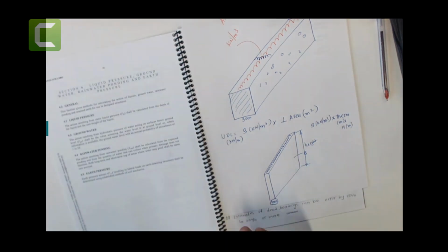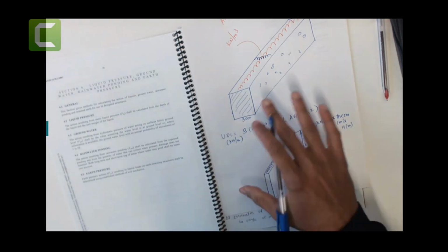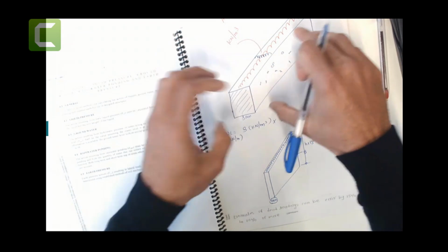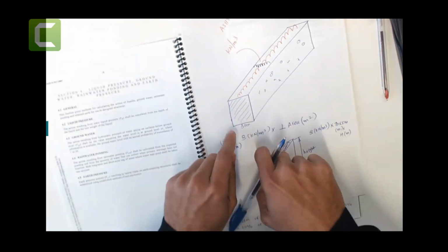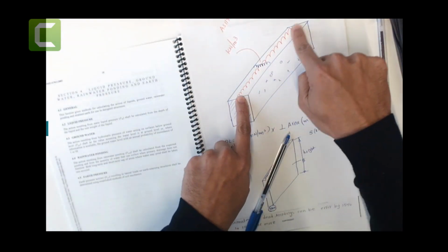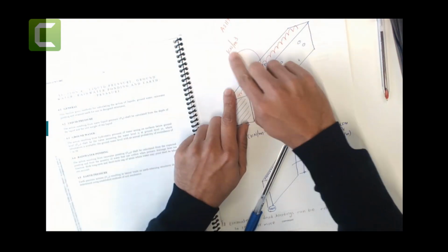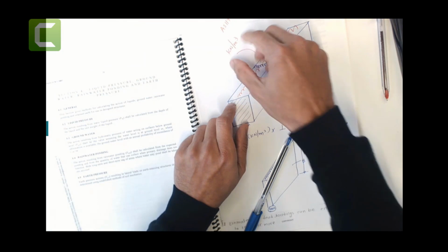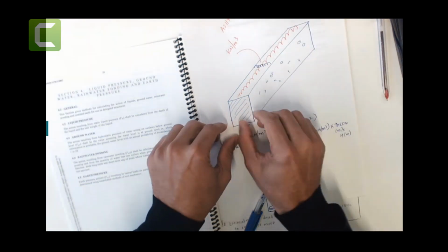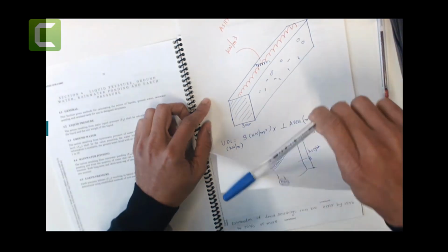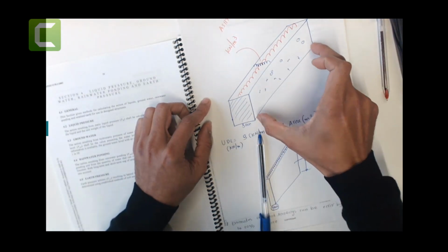We will take examples where I'm going to explain that in detail. So I think you understand the story. If you have a slab or beam or anything and you want to calculate the UDL load due to its own weight, you take the density in kilonewton per meter cubed from the standards times the perpendicular area to get kilonewton per meter. If I want to calculate the point load, you just multiply by the length.